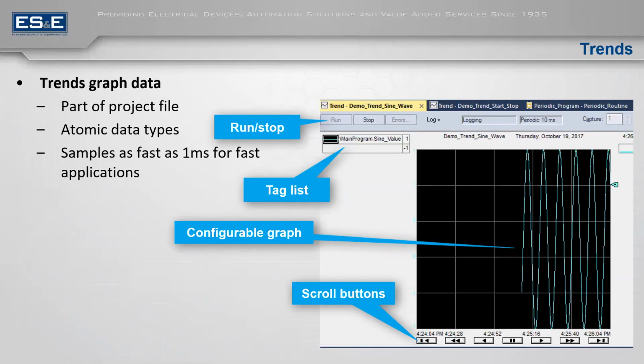I have used this specifically for safety conditions. We were running, and in the middle of operation, our machine would stop and throw a safety fault signal. By the time you look at the code, everything looks fine. You hit the reset, it starts running again. It would do this every couple of hours. We just couldn't figure out what it was. What I ended up doing was putting a trend on my safety signals, both in and out. And I found that my safety input signal had dropped for less than 2 milliseconds. It would drop for about a millisecond and a half, and then come right back. And that was enough to stop all my servos because the safety signal dropped.